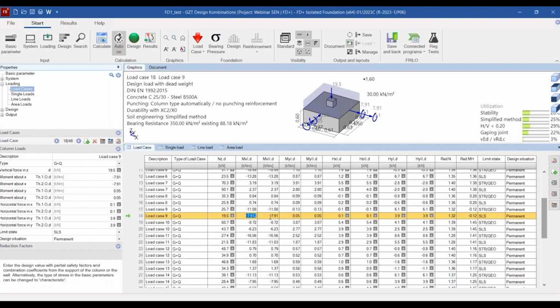So once a nonlinear calculation is done on SCIA Engineer side, you will see that there is a difference between those 2 values, and that's the sign for you that in the foundation calculation you can take these additional internal forces according to a nonlinear calculation into account.